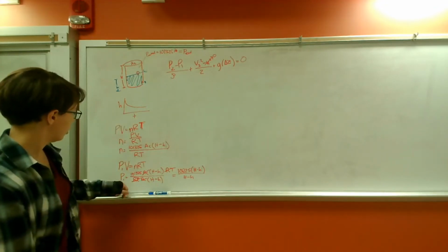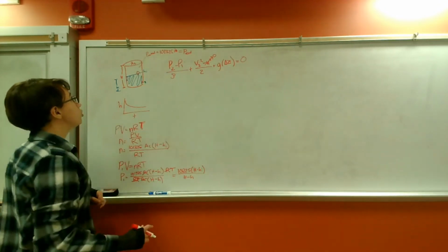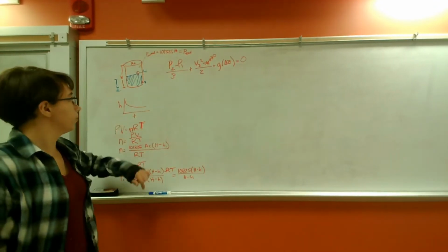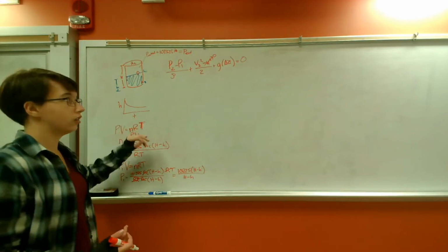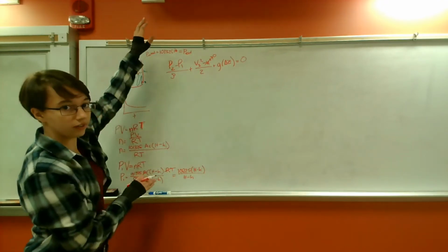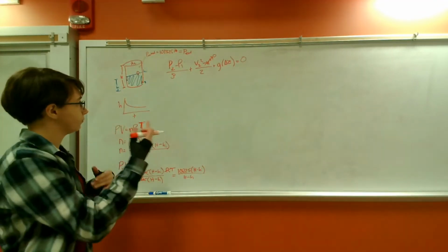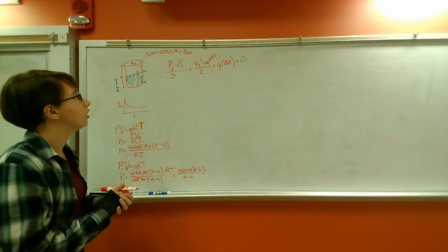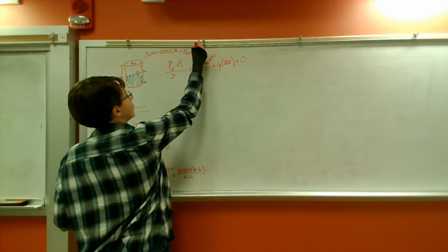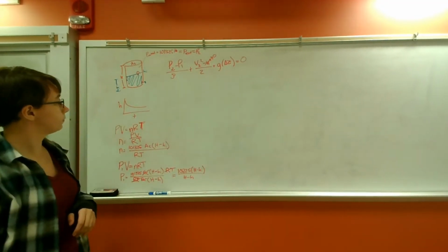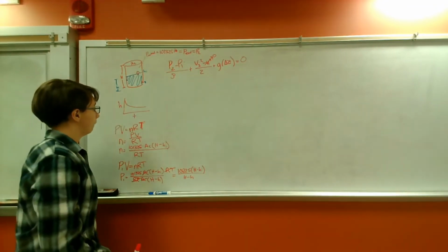Okay. So then we can plug in, we know what P1 is, we can plug that in here. P2 is going to be the same as our external pressure, because this pinprick hole here is a sudden expansion. It goes from this pinprick hole to the entirety of the atmosphere. So that's a sudden expansion, which means pressure is not recovered. So no pressure recovery. So this is also equal to the pressure at that point too. Okay. So we know pressure at 2 and pressure at 1, and we can plug those in. So we're going to do that.